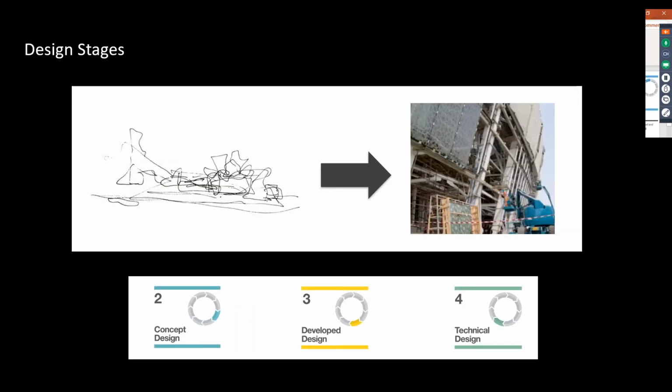Now, another crucial piece of strategic thinking that is crucial to the RIBA Plan of Work is the whole notion of how we move through the 3 design stages, stage 2, stage 3, and stage 4. In some senses, it could be argued that those stages could be a single stage, and certainly in the Plan of Work, we have mapped out how some of the other plans of work across the globe work in that regard. But it is common where a plan of work is used in the construction industry elsewhere across the globe to have a number of design stages so that the design can be incrementally signed off as it progresses.